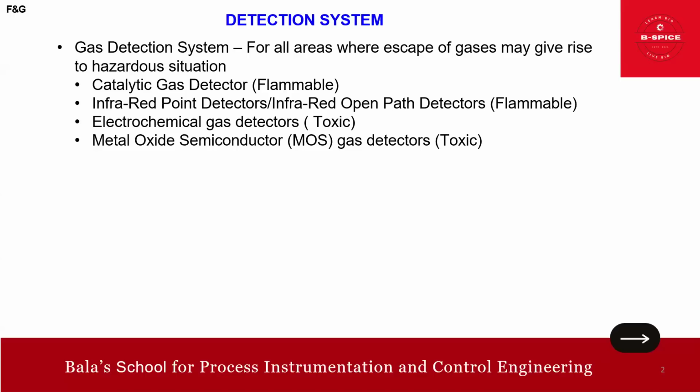And another feature, it has a heater element. A built-in heater maintains the sensor at an optimal temperature, usually between 200 to 400 degrees, to enhance sensitivity and response time. That is the point. And when we talk about the gas interaction, when toxic gas molecules interact with the metal oxide surface, they alter the resistance. That is how it works. This change is measured and converted into an electrical signal.